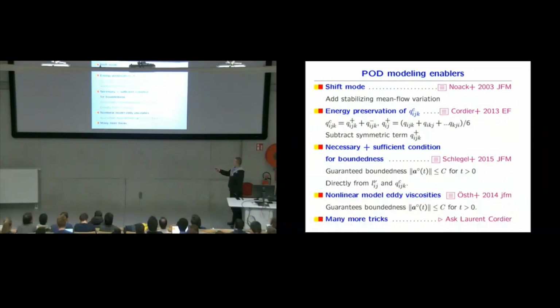So you can decompose the Qijk, the 3-tensor, into one quantity, which is the average, and another quantity, which is the remainder. You need to remove this part because you will always have some numerical error to be Navier-Stokes consistent. This is the remaining part, and this often stabilizes an otherwise unstable Galerkin system. Because the further you go with your mode number, the smaller structures you have, the larger the numerical error, and at some point you will inevitably get noise.